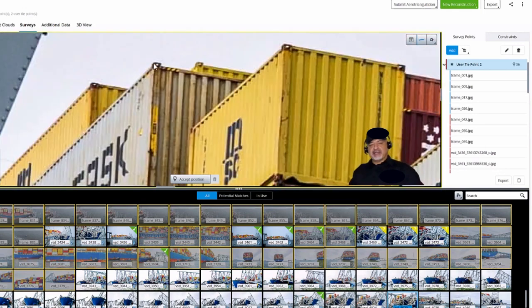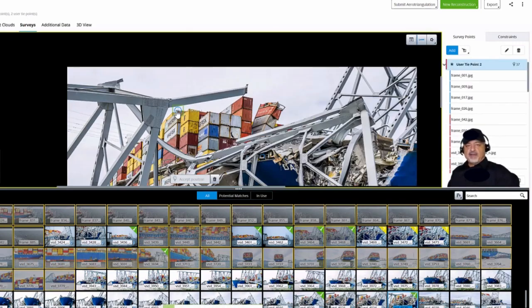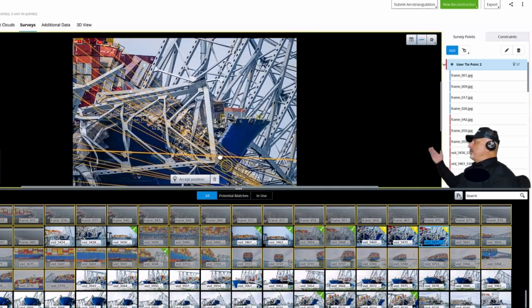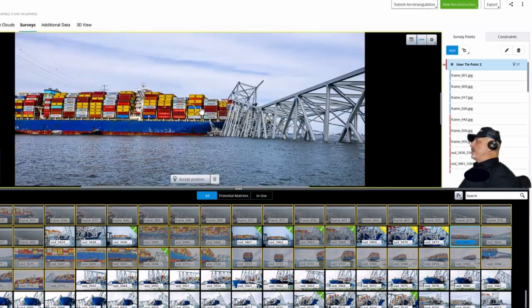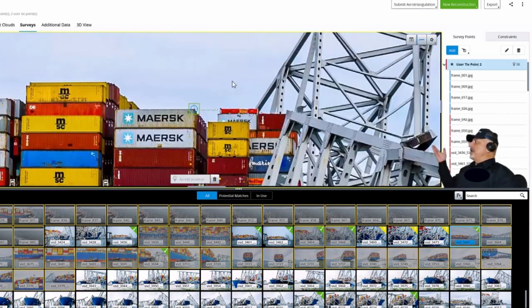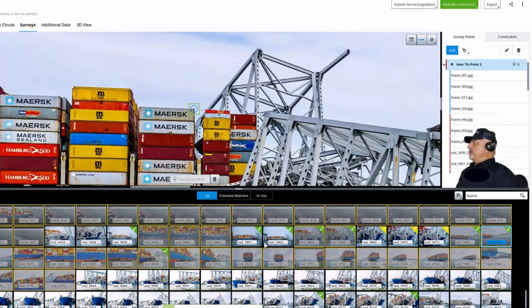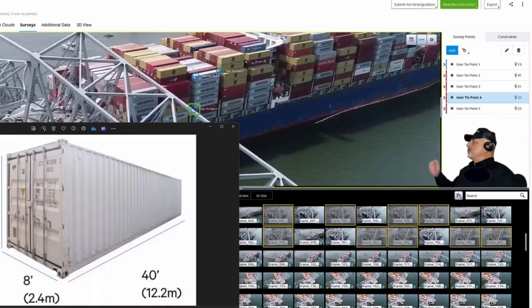model's scale accuracy. Our next step involves refining our 3D model by identifying tie points across the images for 2 main reasons. First, these points help align and stitch the images together more accurately. Second, they serve as crucial markers for scaling, ensuring our digital model matches the real-world sizes.